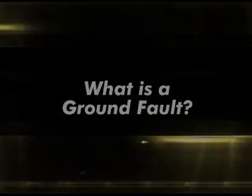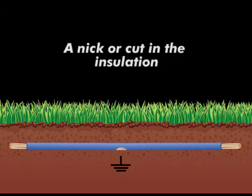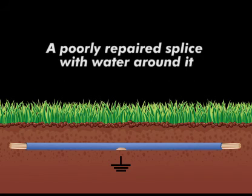What is a ground fault? A ground fault is an unintentional grounding of an insulated wire. What can cause a ground fault? A nick or cut in the insulation, a poorly repaired splice with water around it.